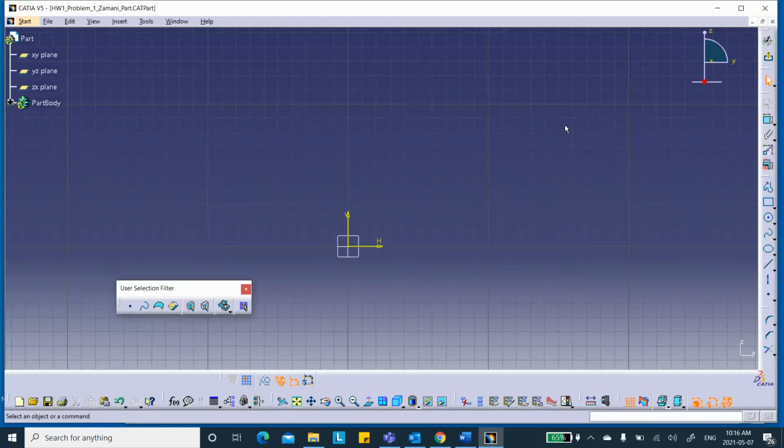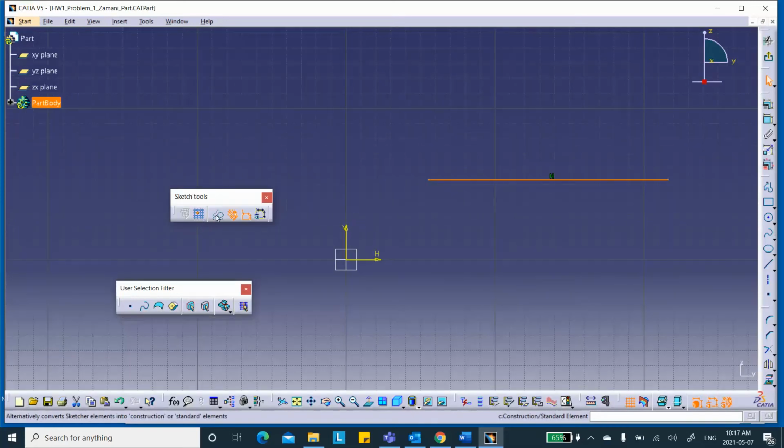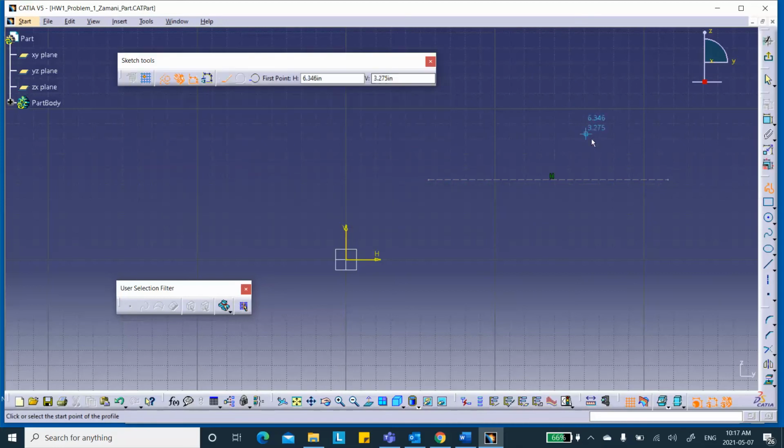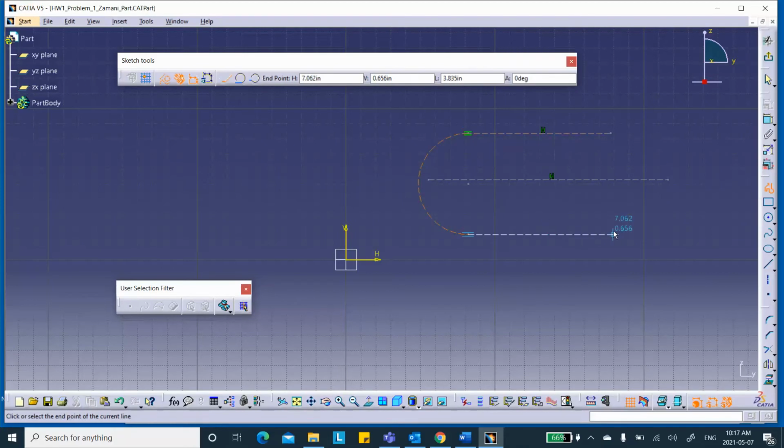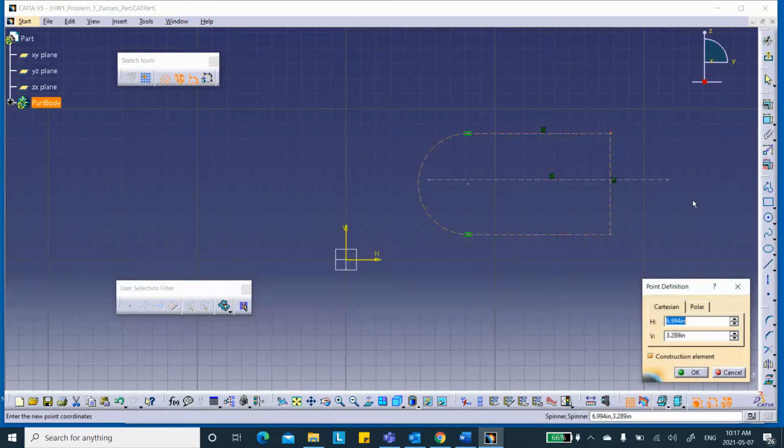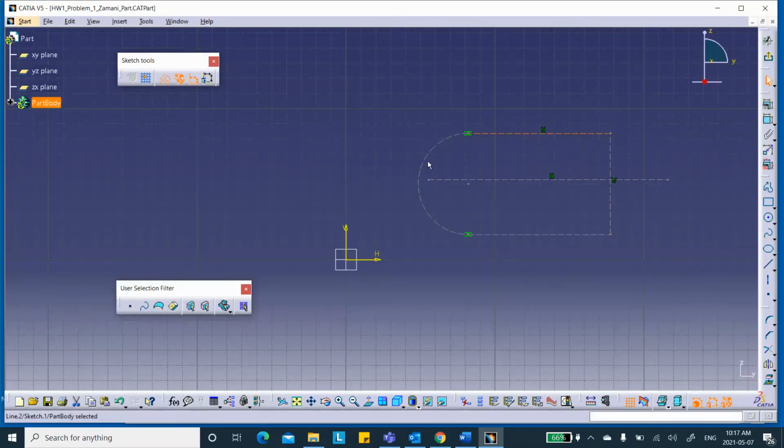Okay. Now, the first thing I'm going to do is to draw a line. This is going to be a construction line. I'm not going to use it for anything else, but it's a construction line. You select it, and let me get this thing out of the way, and that makes it into a construction line. See that? Okay, now I'm going to try to do that section that you saw. So here's how I'm going to do this. Move this thing out of the way. So something like that. I didn't want this thing to be a construction line, so I have to fix it like this. And I really didn't want this to be construction, so I select all of these, this, and that guy. Oops, control. Okay, and turn it into an actual line, not a construction line.